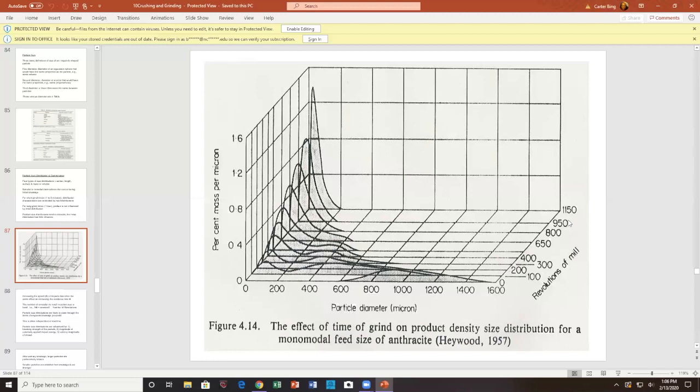For any rotating piece of equipment, you should characterize the action on the material you're trying to process in terms of the number of tumbles or the number of rotations. It's not time that's important. It's what your material has physically experienced.